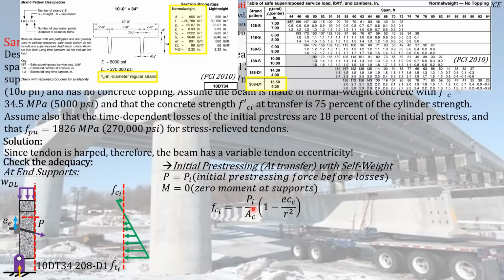And according to the code, you have to remember that the actual stress that will be experienced by the concrete at the extreme pre-compressed fiber is actually a tensile stress, according to this diagram, because this stress here points away from the concrete itself. Obviously, it means it's a tensile stress, and in a similar manner, these stresses that you are seeing here that point towards the concrete itself are compressive stresses.